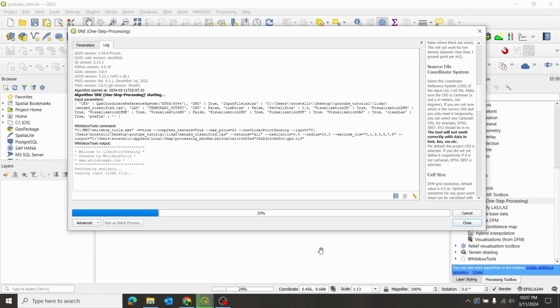Since my target resolution here usually is about a 1/2 meter, that allows me to see: do I have a point in general every 1/2 meter, or is it way denser than that, every 1/4 meter or even more? Could I process this at a higher resolution? Or is it some older USGS data that's really not as good, and I need to back that off to 1 meter?